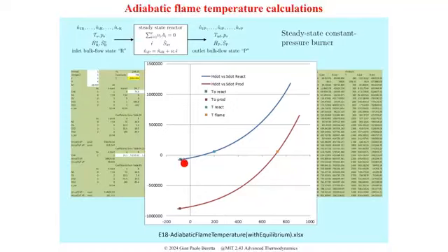It allows you to compute, for example, the enthalpy versus entropy diagram for reactants and products. It can allow you to identify, for example, in this case, I assume the reactants are at 700 K, and to compute the adiabatic flame temperature, so the temperature of this other state for the products. So you can play with this if you like.